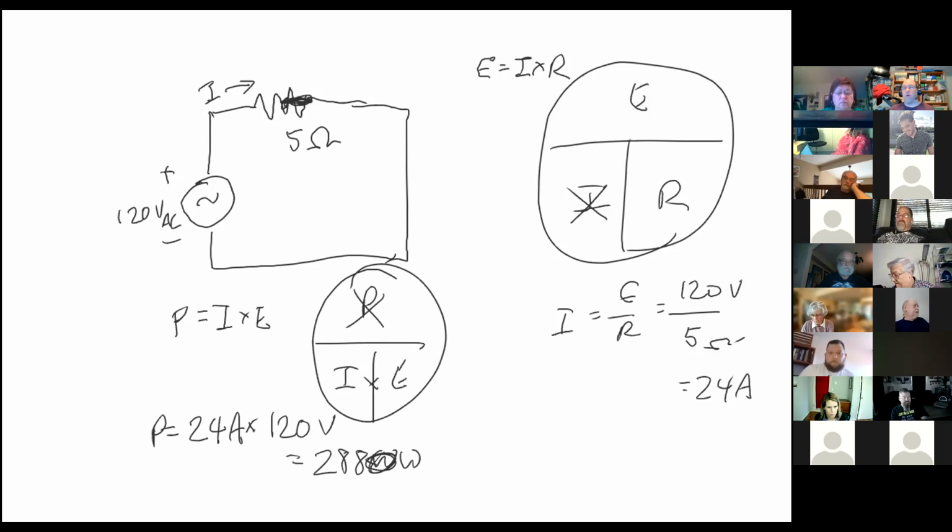Okay, so what problems do we have here? You need one hell of a resistor. Well, yeah, but you can't change the resistor. In other words, there was an internal fault in the resistor that caused it to become shorted out. So you can't change the resistor. So name some problems. This current that's flowing through the wire is now how much current? That is now 24 amps. Can produce a lot of heat.